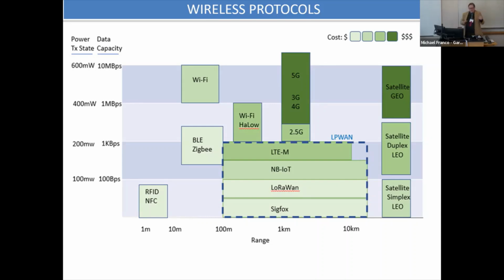It doesn't do a full handshake with the cellular control channels. So what it does is re-register itself every time it sees a tower, so you might lose a few seconds. Okay, these are not made for video, so you're going to have a latency problem with these. Again, I'm focused on fixed, locked in, the longest distance I can get, and the lowest power. These are integral to IoT. The new world of IoT, this is the only way to go. This is slow power. The only way to go.